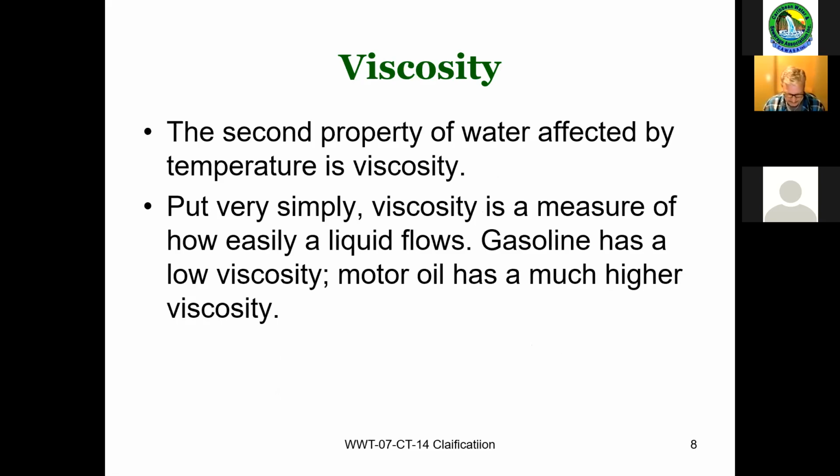That's usually in the clarifier design more so than operations, but it's interesting to understand that a particle will settle faster in low viscosity water, which makes sense. If you threw something into a barrel of oil, it would sink, but it's going to float down really slowly, whereas if you threw that same particle in water, it's going to sink a lot faster.